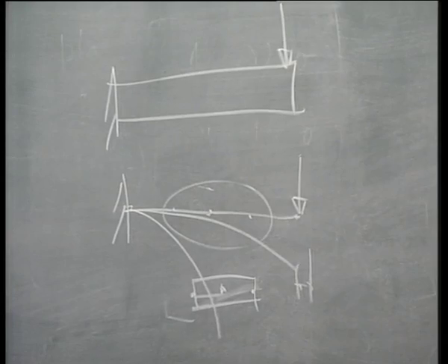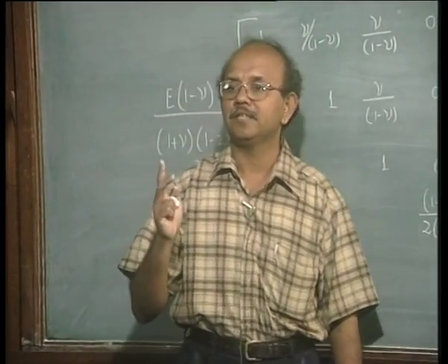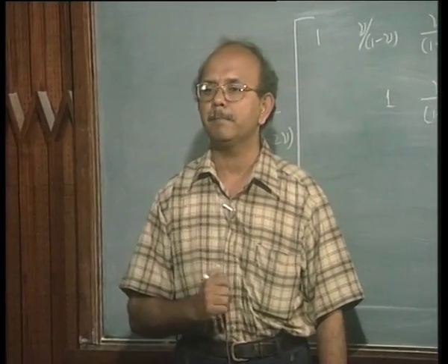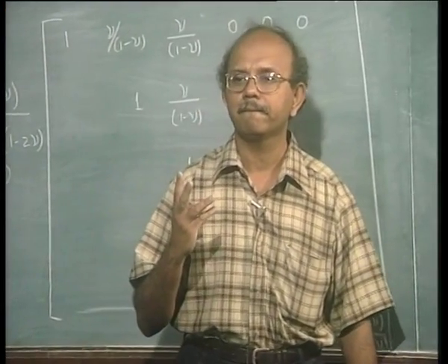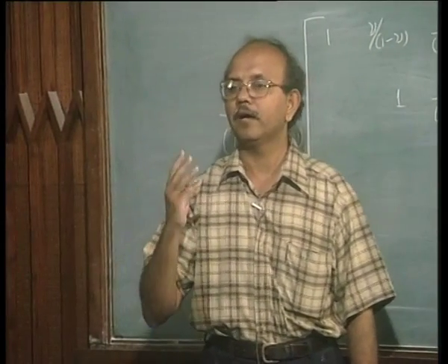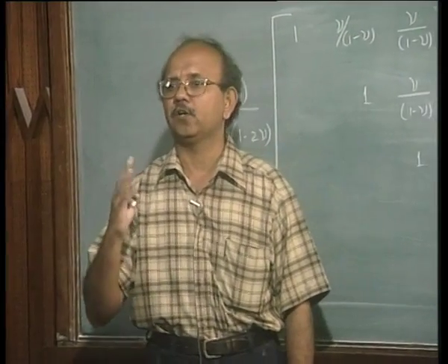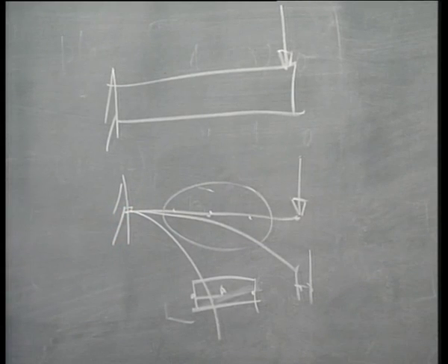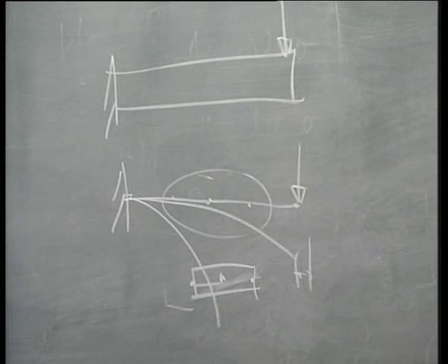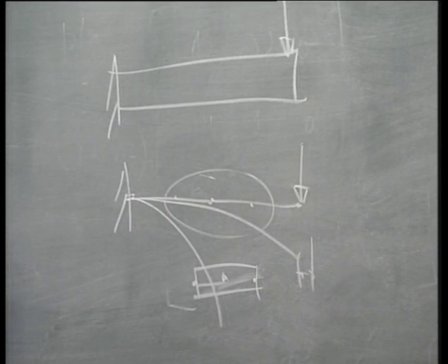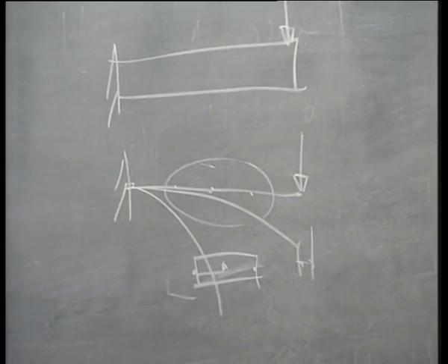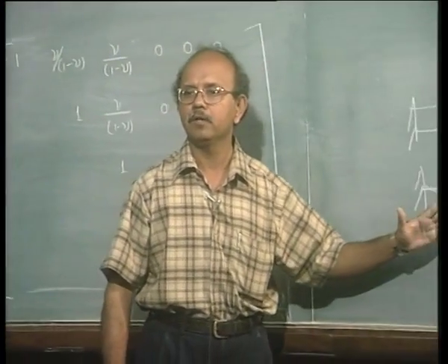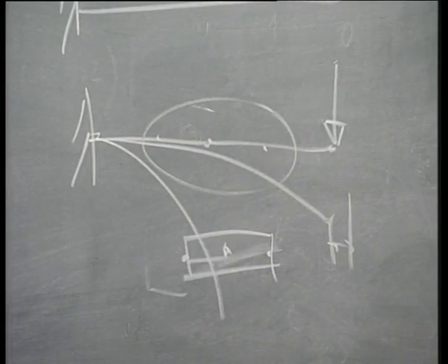So the displacement is W, very good. Some of you answered that the second degree of freedom is theta. Now why did you answer, or how do you know that it is theta? Yes, one end of it is not rotating. That's a very good answer, because when you apply a boundary condition in your earlier classes, you would have said that the slope there is equal to 0, a cantilever beam slope is equal to 0. So in order to specify a boundary condition, you obviously need a degree of freedom, and hence this beam, a two-dimensional beam, let me call this a two-dimensional beam, should have theta as well as a displacement.